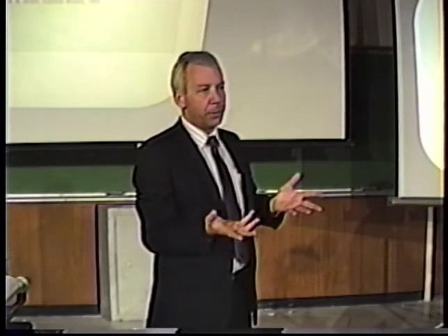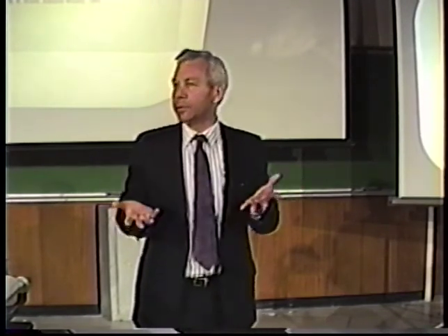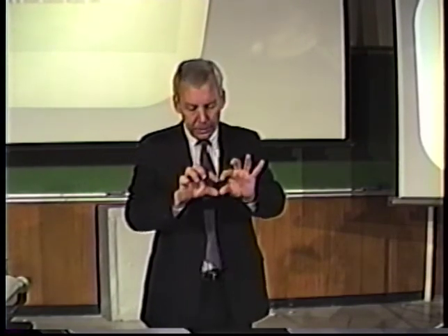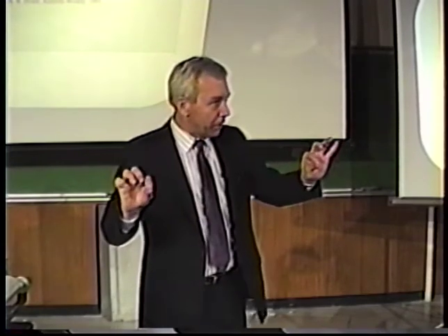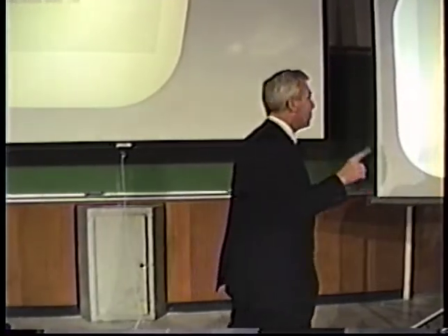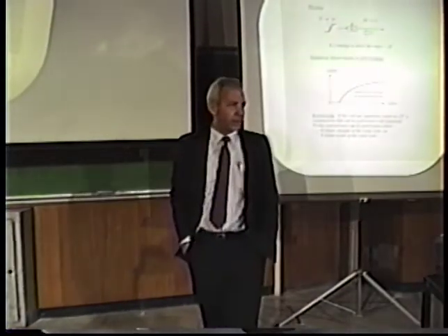Or maybe the problem can be formulated so I can do 1,000 multiplies at once. It might not seem to make any difference, but it makes a difference of a factor of 1,000 in what the computing engine costs. That's because if I have 1,000 multipliers, each one of which can take a microsecond instead of a nanosecond, the cost per operation is 1,000th as much.